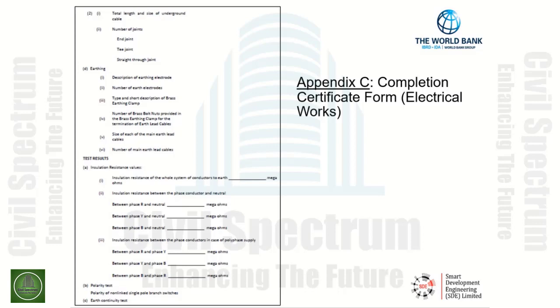the old existing color code is indicated with respect to the colors of phases. This is the old existing IEE standard. A note to the code user with respect to the completion form here, any new installations would need to be changed to the new color code indicated in the IEC standard.